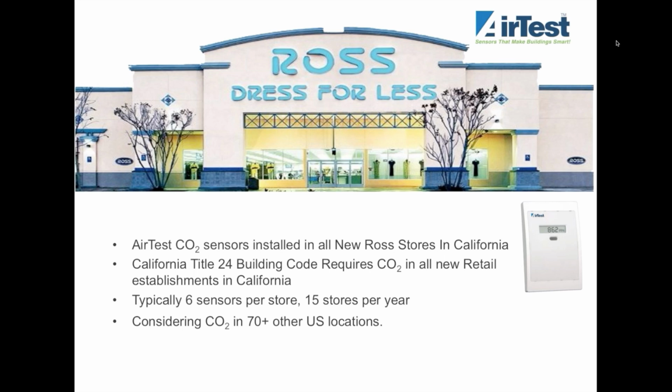And then actually anything like a store that has design density greater than about 25 people per 1,000 square feet, the building code actually requires CO2 sensors be installed. And the reason for this is they did the calculations, and the energy savings for using CO2 in this kind of application is such a no-brainer that they decided to make it part of the California Energy Code or Building Code.